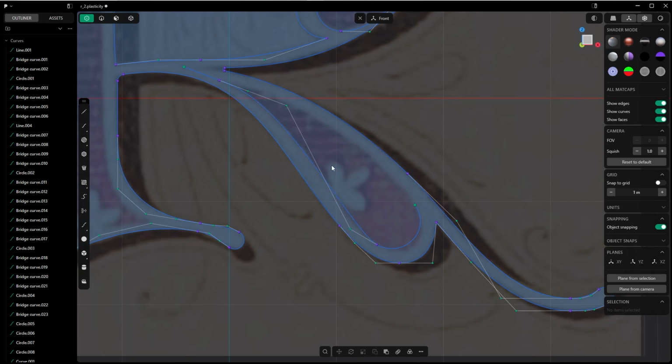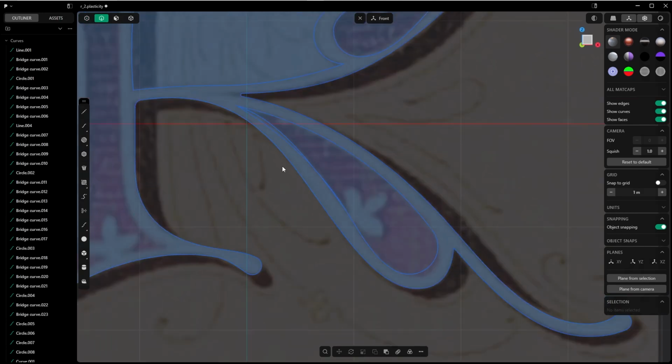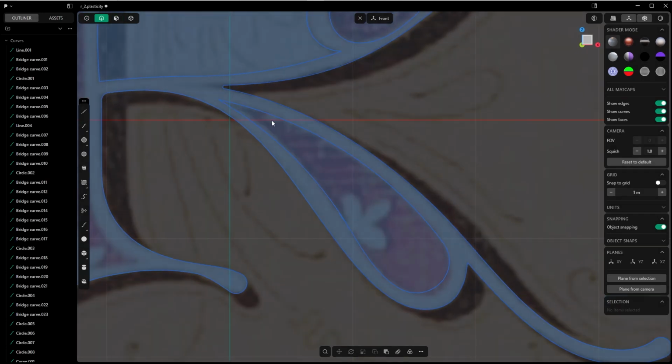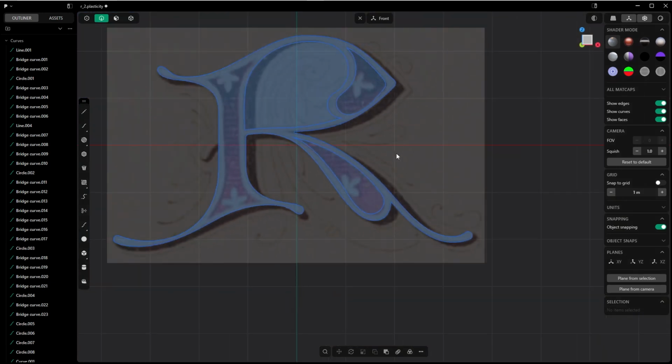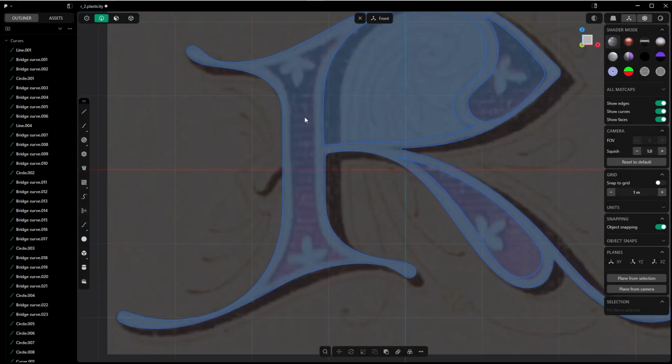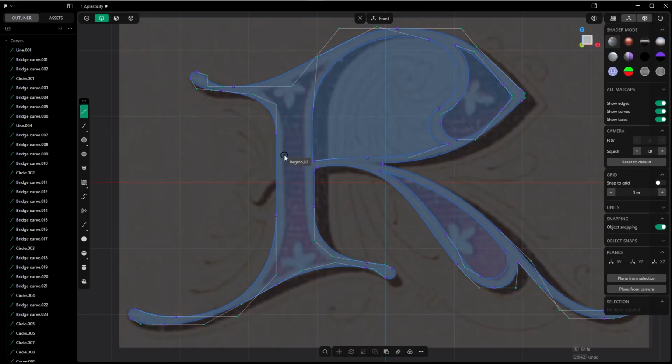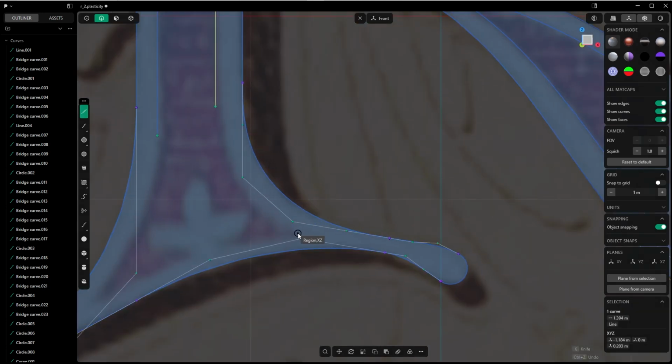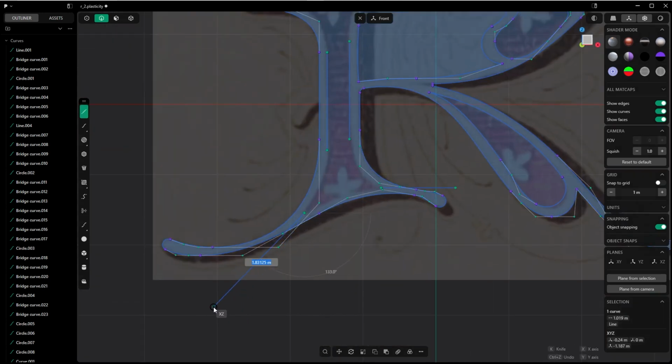So I will say okay and create another line which I will use as a trimmer. Press Alt H to bring back the rest, and delete this one. Okay, that's the last piece. And of course I forgot to do this part. That's important. But first of all, let's make the inner part. Again, let's press Tab twice, type in 135, so we have a perfect 45 diagonal line.